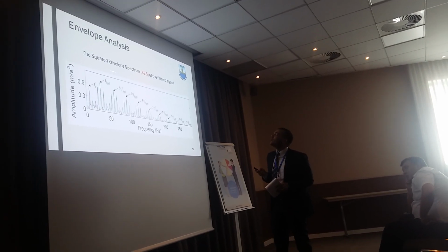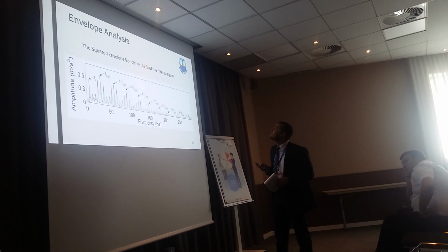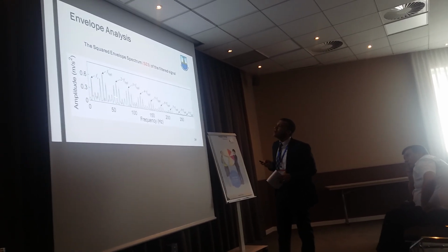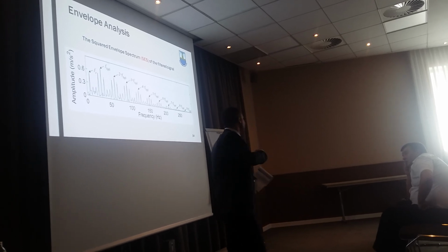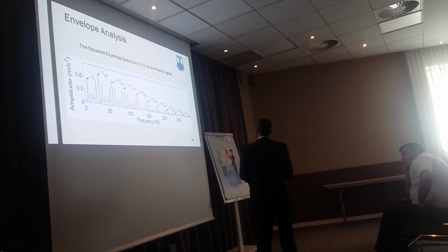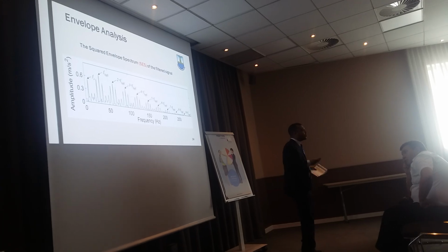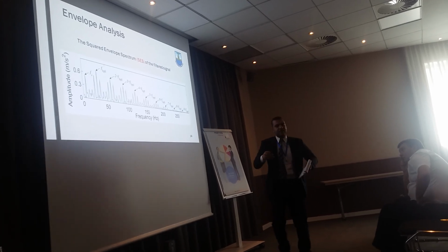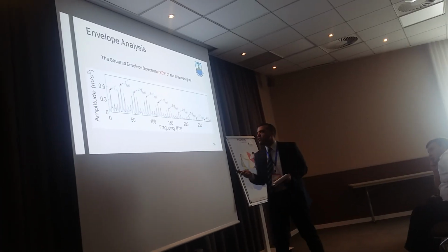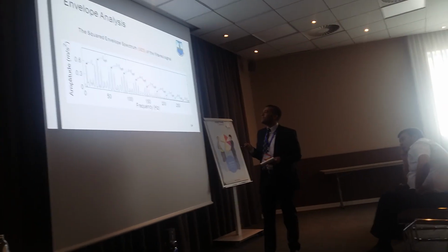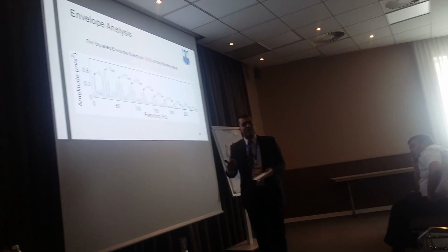And the squared envelope spectrum showed up to the 9th harmonic of the bearing characteristic frequency, which shows that the Gini index and the proposed methodology are so powerful. Because as many harmonics as you see, that proves the strength of the algorithm, because many harmonics ensure a faulty bearing case.